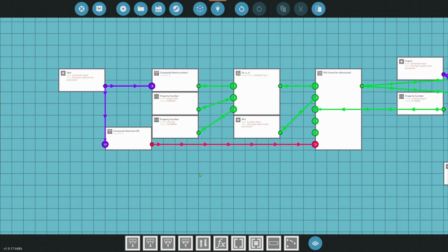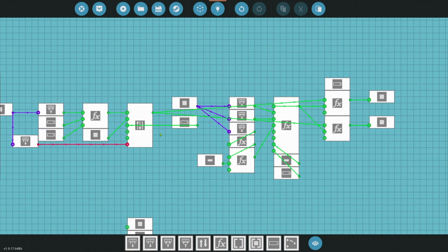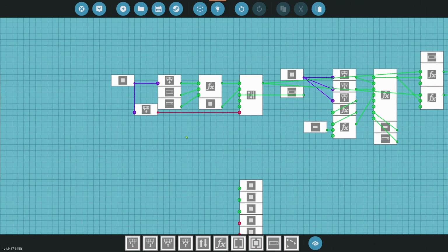When we shut 6 off, the PID is going to go off, which will read a 0 value to the engine, and that will starve our engine of air and fuel, and then our engine can no longer run. It will shut our engine off. So that's why we're doing that.